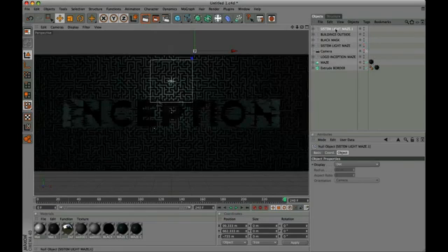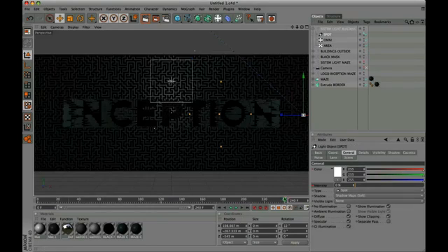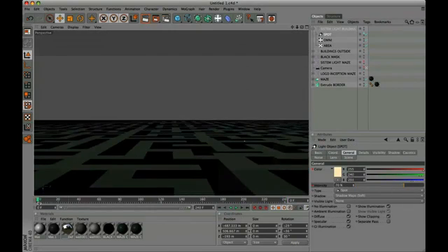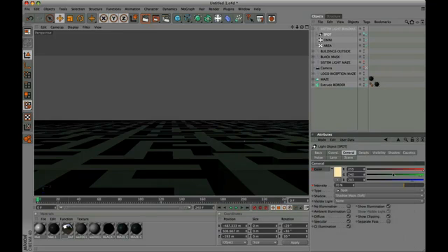Duplicate, and rename the new group Light System Buildings. Click on Spot and go to frame 0. And change the color animation with 230, 195.